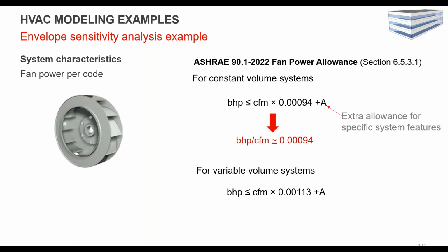There's also these add-on static pressure credits. So if you have high filtration, MERV 13 or MERV 16, or carbon cleaning or heat recovery, you get additional credit. So again, if you have those things, you would tend to include them as static pressure credits. Here, you get a little bit higher fan power.